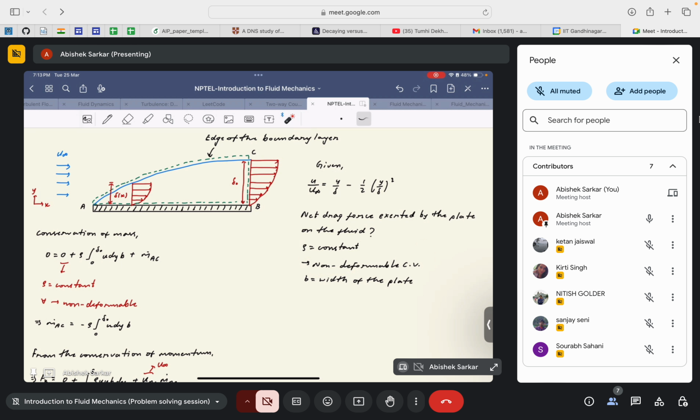In this case, since the fluid flow is coming through this direction, of course mass is going outside from this particular surface, from this particular edge, so it is net mass outflux. But here we do not know, so it can essentially be a net influx. It will essentially be net influx, because since it's a closed edge here, mass has to go through this particular edge for the mass conservation to be satisfied.